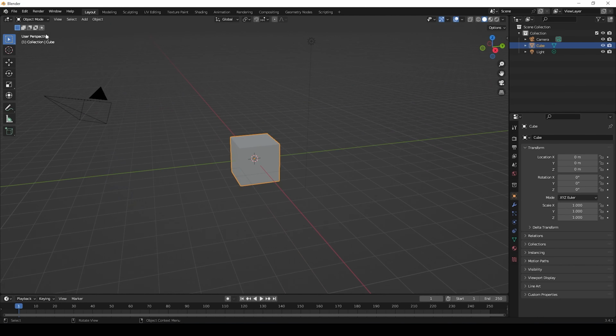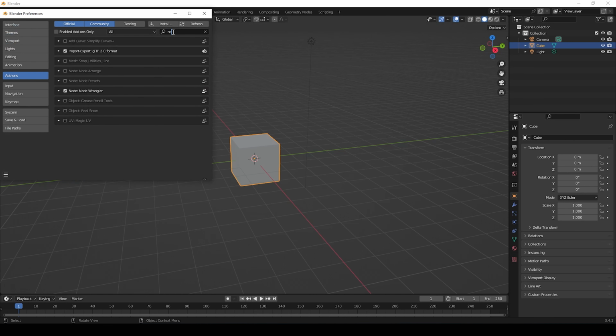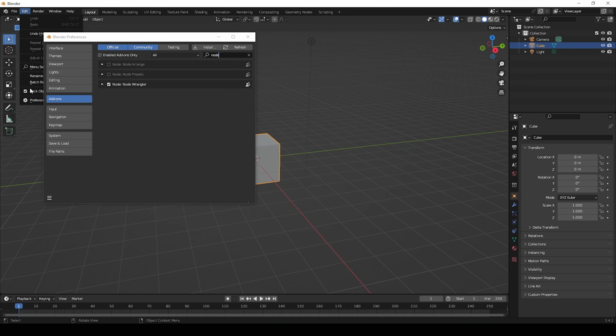So before I get started, I first need to turn on a couple add-ons. The main one that we need for this build is going to be Node Wrangler. So if you just go to Edit, Preferences, Add-ons, and type Node in, you want to make sure Node Wrangler is activated. You might make sure that 3D Print Toolbox is also available to you, and then Images as Planes, Import Images as Planes. Each of those might be important as we do some design here with our satellite.